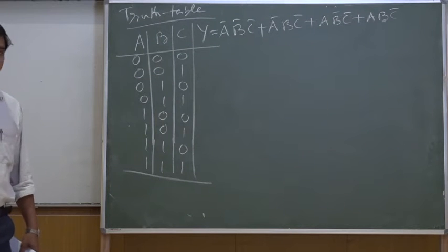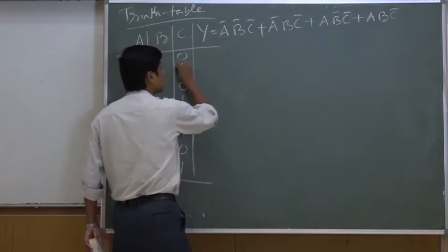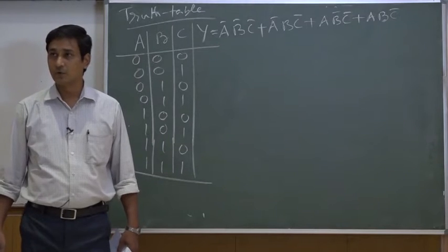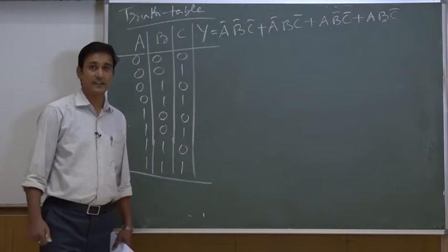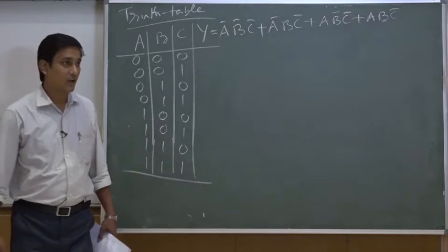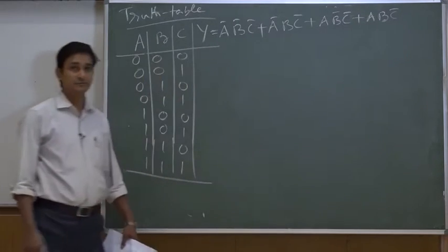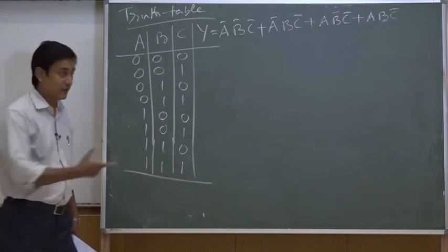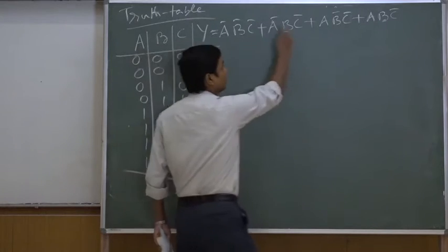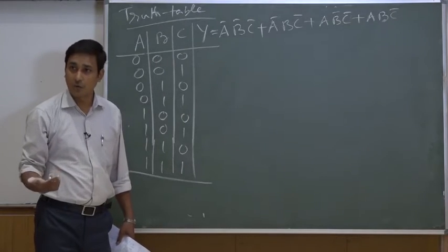Now, if I ask you to implement this in the Karnaugh map, who will be existing there? You need to find that out. Please define this y from here. These individual min terms, which are the product terms, are ORed with one another. So, if any one is 1, then the output will be 1.